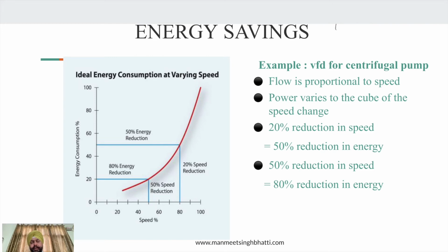Just in case the pressure drops or some leakages happen, you want to make sure that the 7 kg reaches your farthest point of the plant. So that's the basic philosophy that we have been using. But sometimes, if the system is very well designed, or it's a new design, there are no leakages in between, and the 10 kg automatically gets passed on directly to the 10 kg at the end. So that 3 kg extra pressure that you are providing is actually a loss of energy.